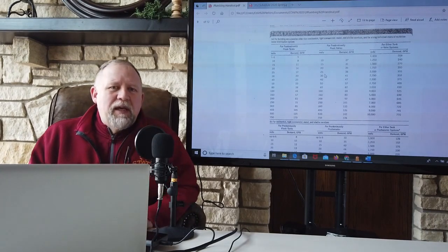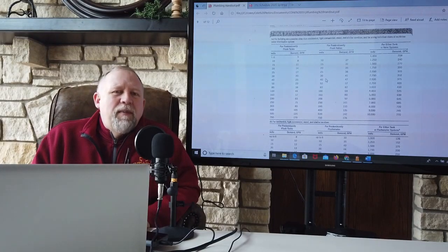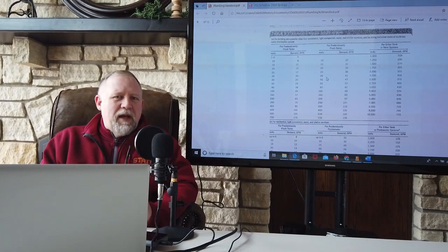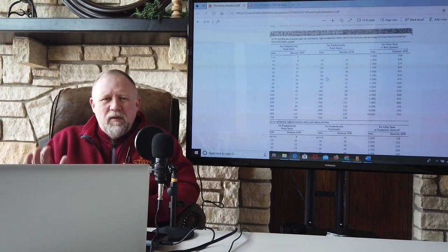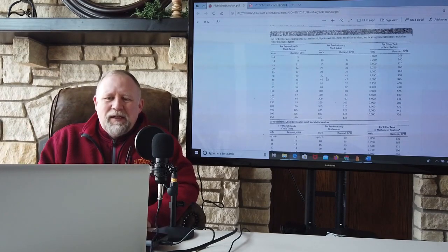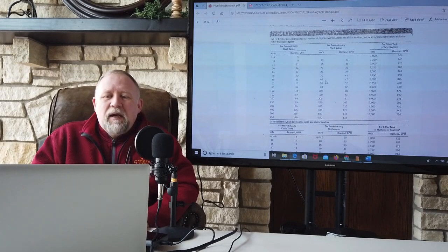Table 8.3 is a conversion table. It goes from water supply fixture units into the demand in gallons per minute. Remember, water supply fixture units aren't real units of measurement. They're kind of magical, mythical, nonsensical. They're not a real unit, but they are used to get the average flow rates that we can expect at different types of occupancies.